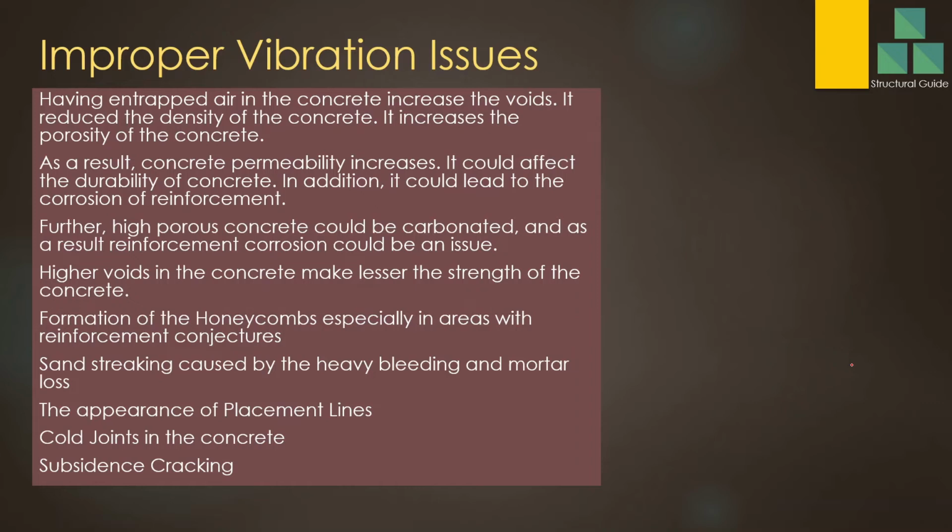It directly connects with the durability of the structure. As a result, concrete permeability will increase. It could affect the durability of the concrete and could also lead to corrosion of the reinforcement. The higher the porosity in the concrete, the easier it is for anything to penetrate into it. For example, for the carbonation process carbon dioxide needs to penetrate the concrete. The process will speed up, and the carbonation front will reach the reinforcement very easily and very fast. If the concrete is porous, then corrosion of the reinforcement could occur.